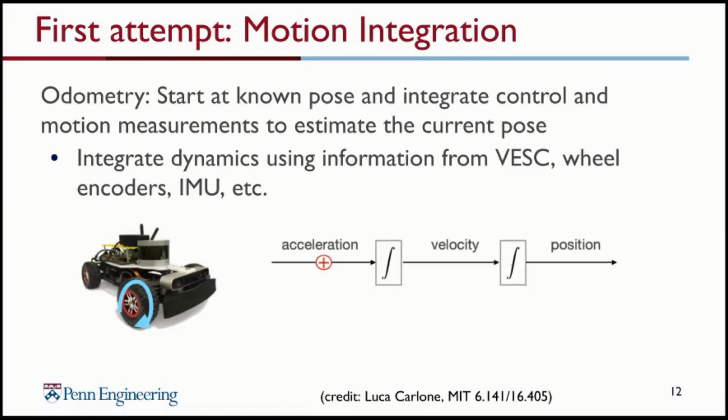How this works is that when we give the commands for movement, this is used by the VESC unit and translated into lower level commands that control the acceleration and deceleration of the robot. The VESC keeps track of the acceleration that is achieved, and this is integrated to obtain the velocity. And finally, the velocity is integrated to give us the amount of movement since the robot first started.